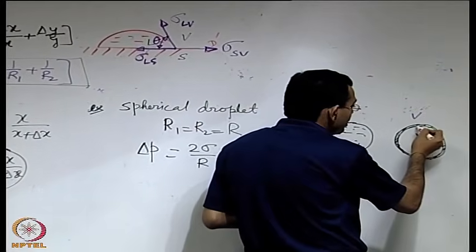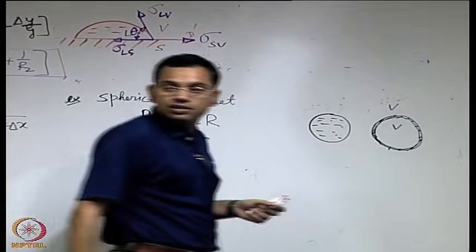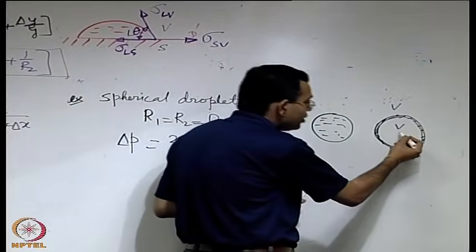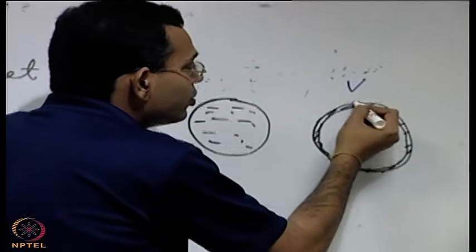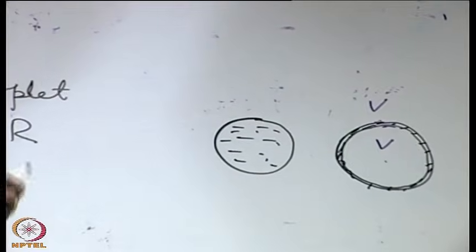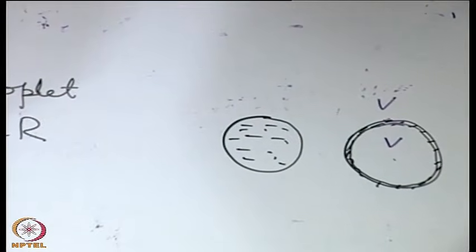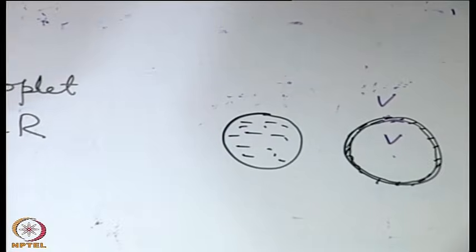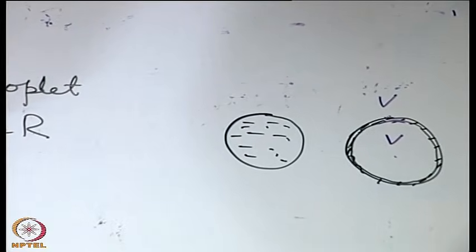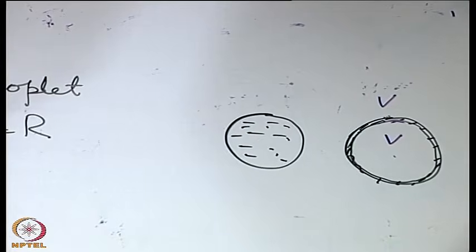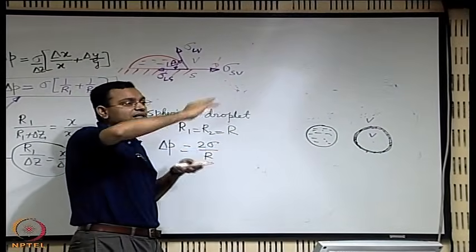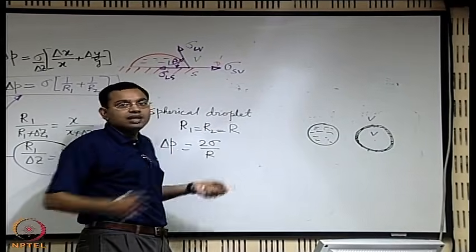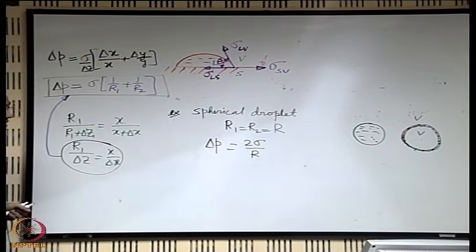So, you have basically two vapor liquid interfaces to consider. One is as you jump from the inner vapor to this liquid line, and then you jump from the outer liquid to the outside vapor location. So you have two interfaces which are formed because of this one. So maybe this should be multiplied twice to get the net pressure difference. So you can see that depending on the physical situation this needs to be adjusted, but this basically talks about that if there is one interface, across that interface if there is a pressure difference, then how can that pressure difference be related to the surface tension coefficient.